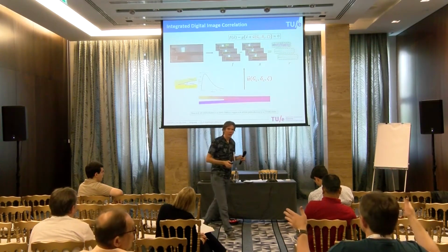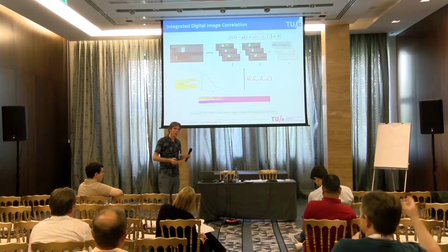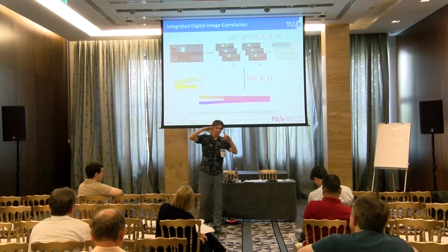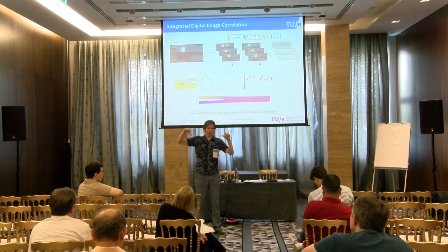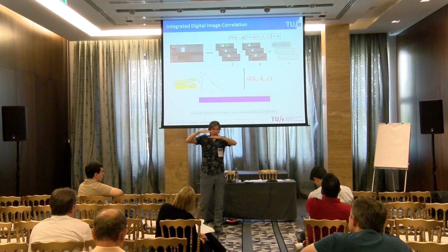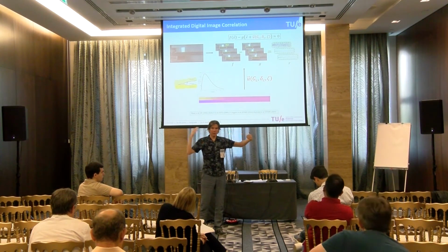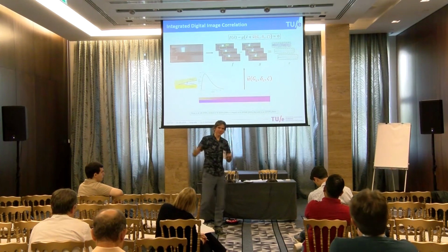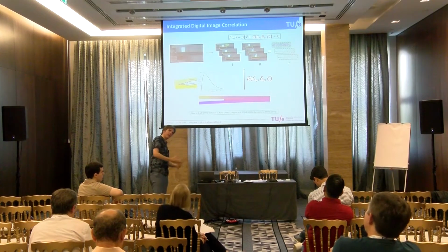Do you need a larger region of interest for the high mode too? No, because I didn't mention this so much, but our region of interest is smaller than the process zone. You're just looking at one spot while the crack comes by. Initially, in the first time frames, you see the initial part of the crack, and then while the crack is going down, you take multiple images, and we correlate all of the images at the same time. So all of that data is in there, just not in one frame, and that's why we can correlate with it.